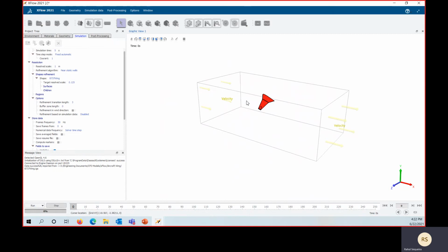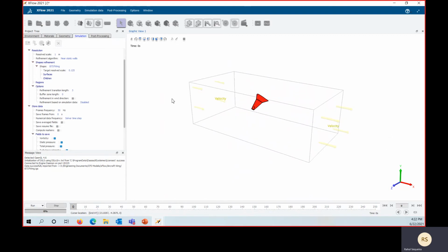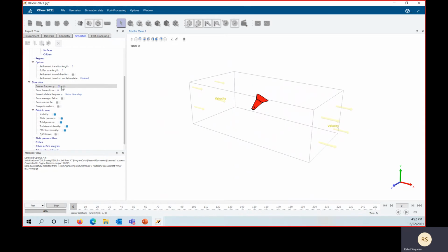So at the geometry, the mesh will be refined 10 times further. No, it will actually be refined 3 times further, because if you do 1 divided by 2, it becomes 0.5, divided by 2, 0.25, and then 0.125. So it'll actually be refined 3 times further. My bad.